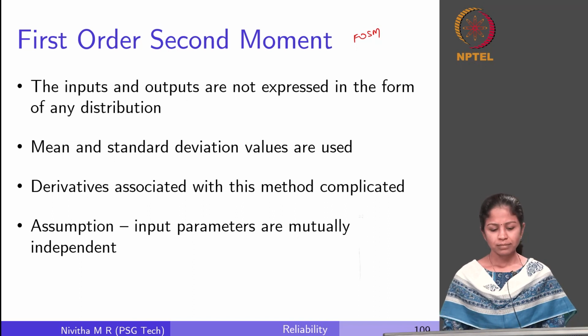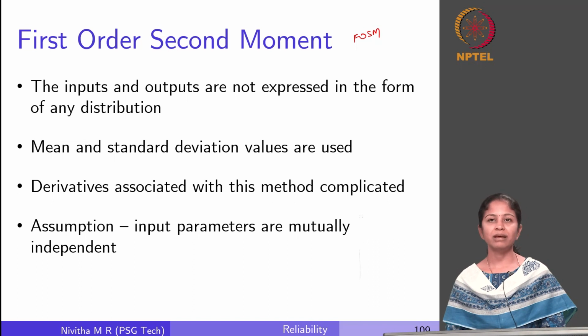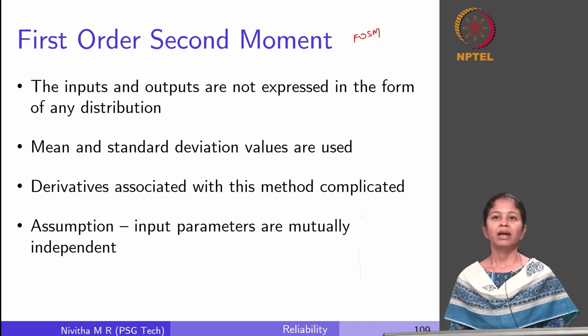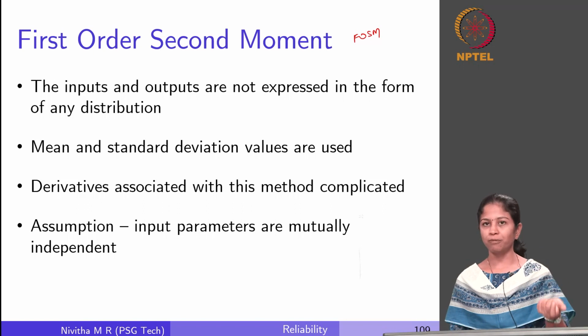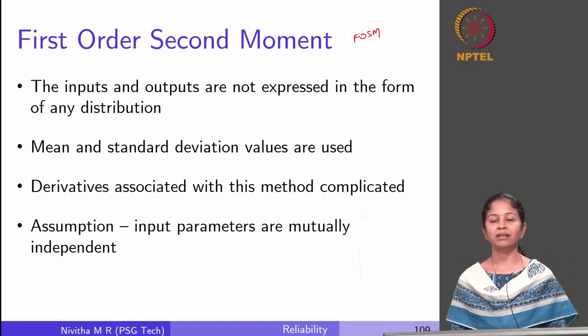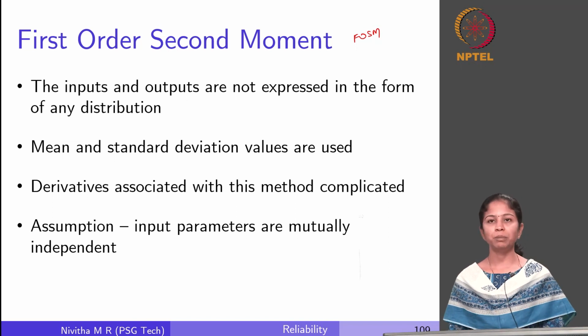then a lot of post processing is associated with arriving at the equation. And here there is an assumption which is used, which is nothing but the independence of the input parameters, right. But we all know that there is a lot of relation between the input parameters, especially with regard to pavement design. So when we are seeing the Monte Carlo simulation, again I will show you, we will be considering the interaction terms, right. Interaction between modulus of one layer to modulus of another layer, modulus of one layer to thickness of another layer. So there are going to be a lot of dependencies.